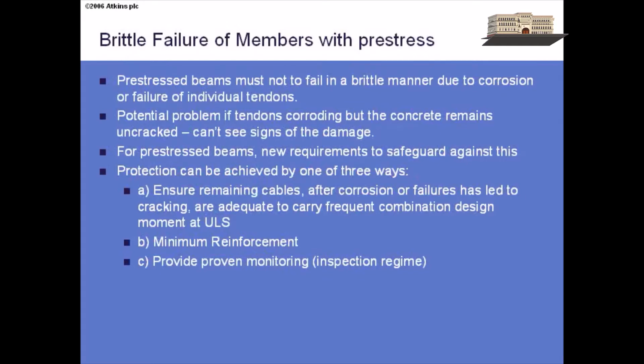What this is supposed to be around, there was some concern that what could be happening with a prestressed beam is you may well have the tendons in there stressed and corrosion is going on and you don't know about it, and the wires are busy breaking and deteriorating, but actually your traffic is relatively light, and although all these prestressing strands are going, the beam is actually just standing up on its tensile strength, the combination of the tensile strength and a bit of pre-compression. The concern is, if that's going on, that suddenly you get a bigger load and the tensile strength is lost and you've lost so much pre-stress that suddenly all the pre-stress fractures and the whole thing just collapses in a brittle manner.